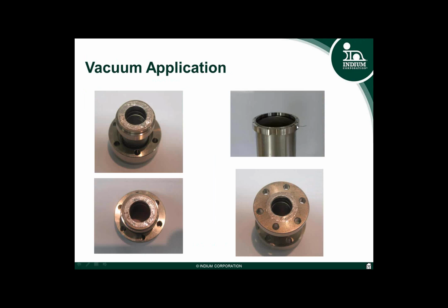Once they're wrapped together, the indium itself would be compressed between the applications, and indium would actually self-wet to these two mating surfaces, and it's those self-wetting properties of the oxides wetting onto the surfaces that would perform this airtight or gas tight or liquid tight seal as required.